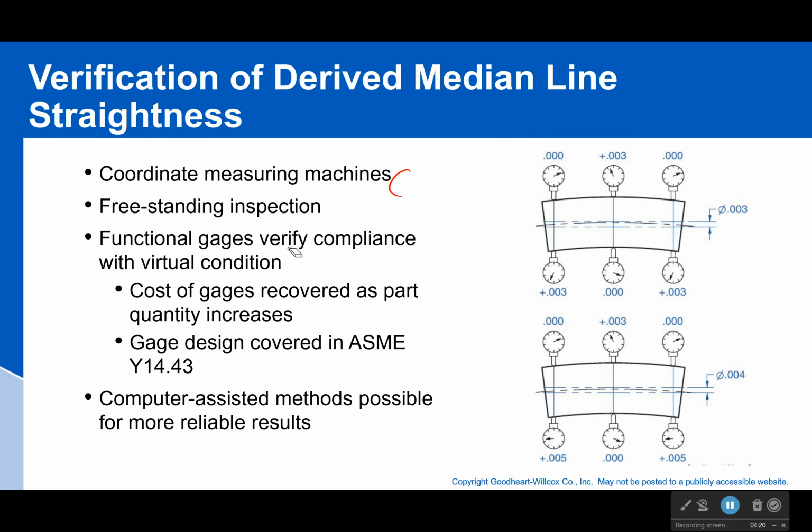Computer-assisted methods are probably going to be the most reliable, though. So I would suggest you use them. We have plenty of machines, like these coordinate measuring machines, which are amazing. It's where you're going to tap various points on the surface, and then it will know exactly the size and location of all the features, and then with that you can determine if it's passed or not.